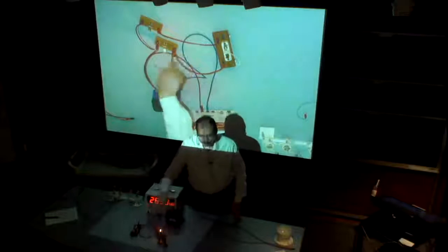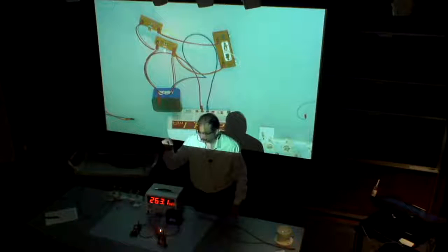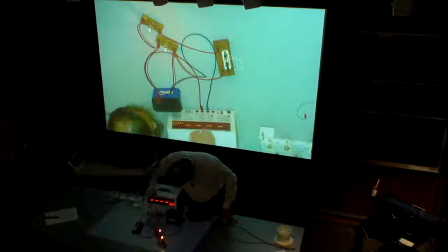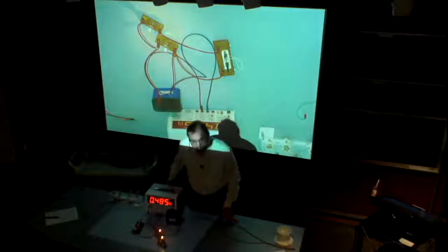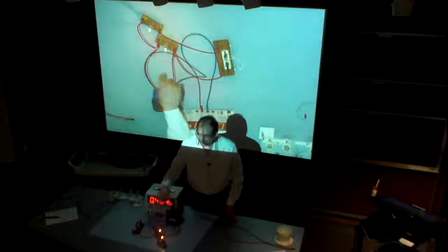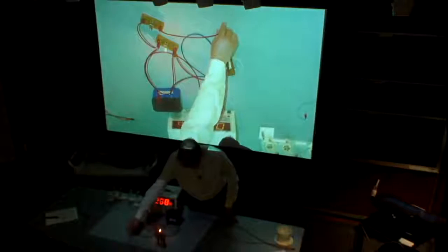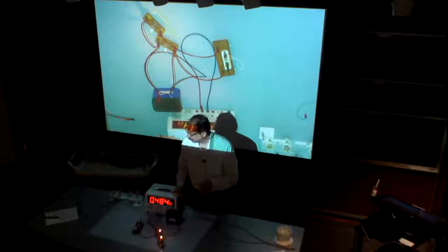By adding an extra element in parallel, we're decreasing the resistance. And when resistance decreases, but the voltage supplied is the same, how does it affect the current? I equals V over R. The denominator decreases. You see, it's too high. I have to switch the scale to this one. Because the bulbs are identical, the total resistance of this circuit now is equal to a half of the resistance of a single bulb. So by adding an identical resistor in parallel, I cut resistance in half, which means I double the electric current.